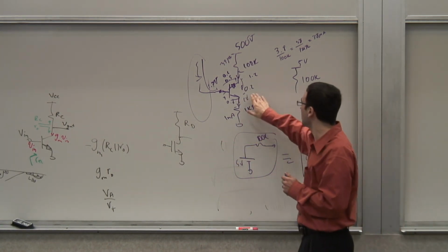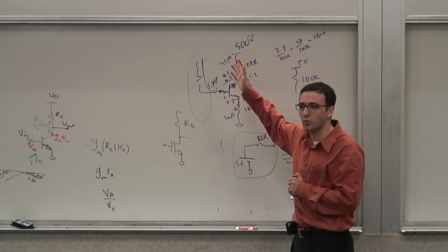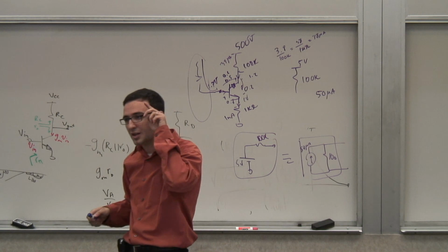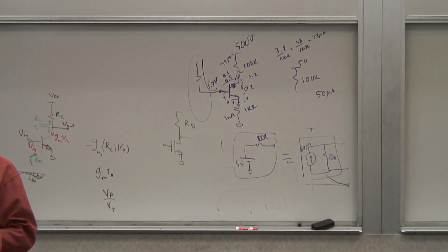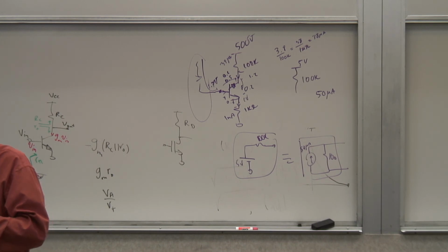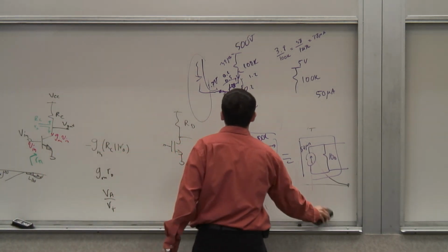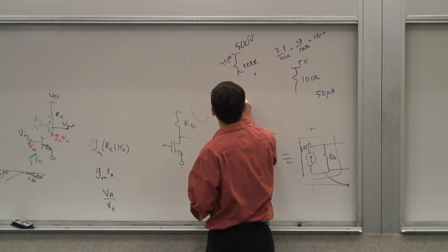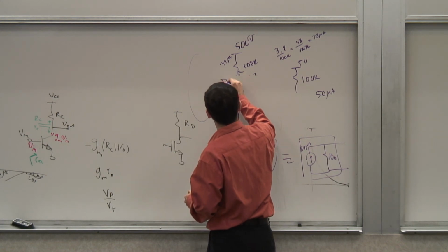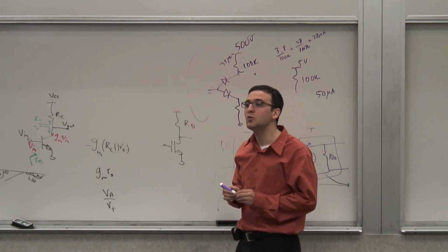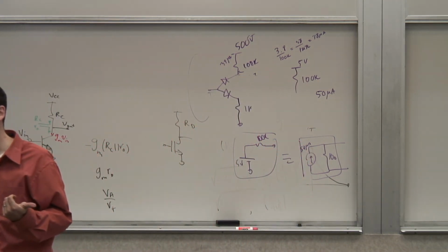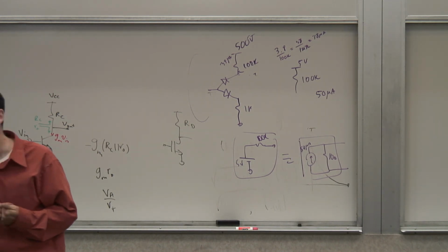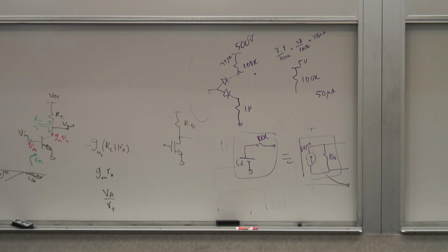Instead of saying 0.1 or 0.2 volts, say that this junction is forward biased by 0.5 or 0.6. Because that will force you to think about this junction as a forward biased diode, as opposed to thinking that there's a little thing there, 0.1, 0.2. It's a forward biased diode. In that case, the way to analyze the circuit is simple. I'm not worried about that stuff, and that circuit is behaving exactly like this. So this is one circuit where my two diode replacement of the transistor does exactly the same thing as the transistor, because the transistor is not really transisting anymore, because that behavior is gone.